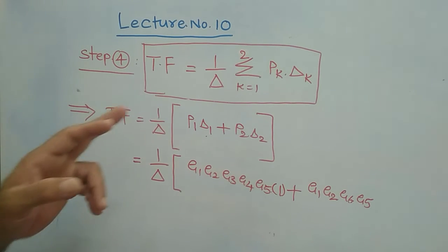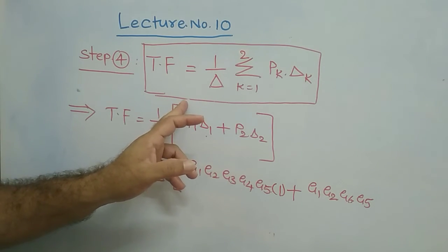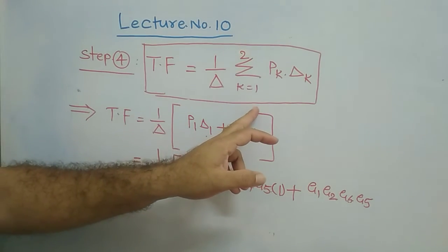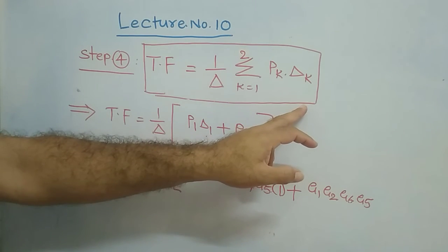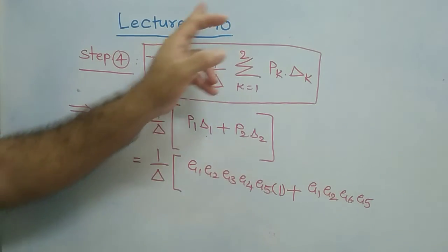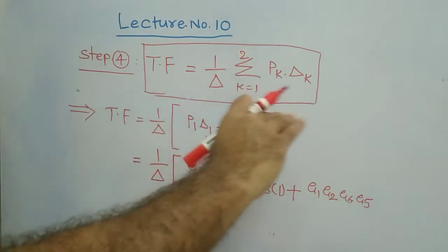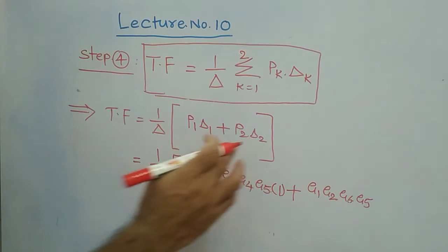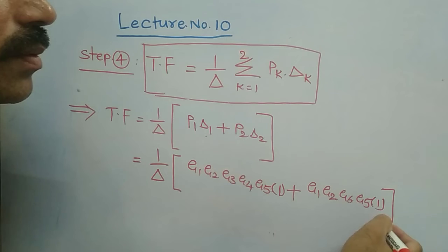Is it not? Again, the second loop is between node 3 and 4, and at node number 3 the second loop is touching the second forward path. And consider the third loop, which is between node number 4 and node number 5; at node number 5 the second forward path is touching here. That means all these loops are touching the second forward path. Therefore, all the loops are touching, so the value of delta 2 is also equal to 1. This is what your delta 2 is.